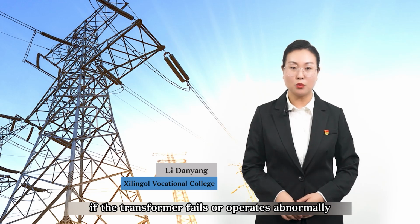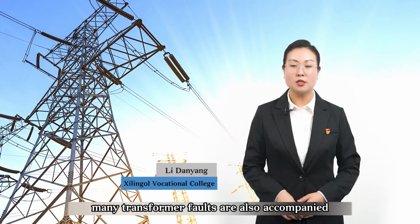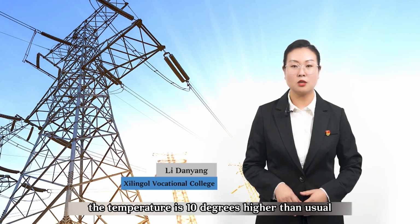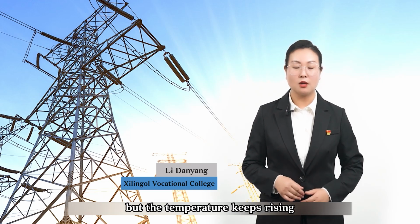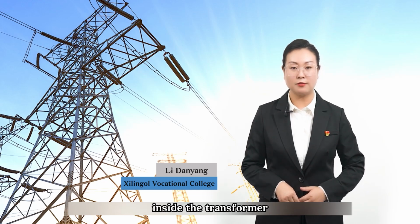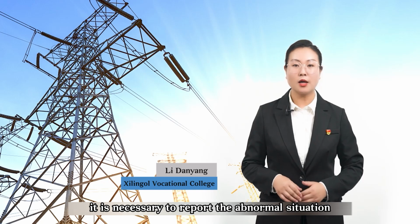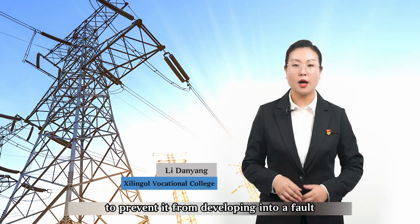If the transformer fails or operates abnormally, the sound will become abnormal. Many transformer faults are also accompanied by sharp temperature rises and changes in oil color. If it is found that under the same normal conditions the temperature is 10 degrees higher than usual, or the load remains unchanged but the temperature keeps rising, it is considered that an abnormal phenomenon has occurred inside the transformer. When abnormal operating phenomena occur in the transformer, it is necessary to report the abnormal situation in a timely manner, analyze and handle it to prevent it from developing into a fault.